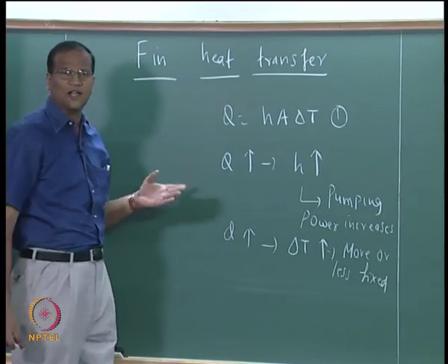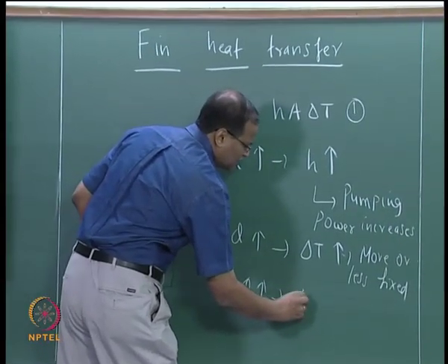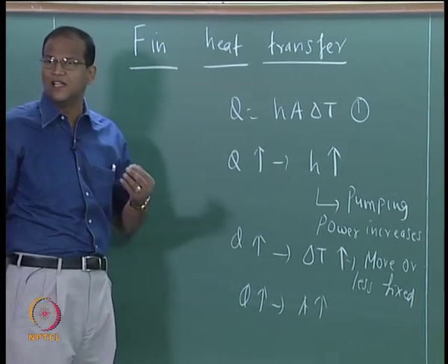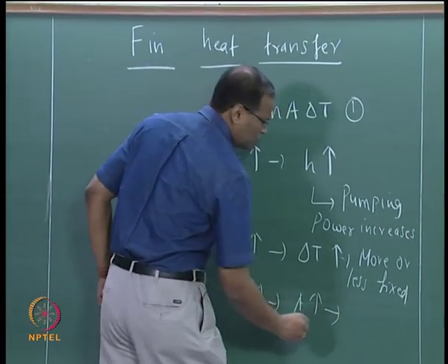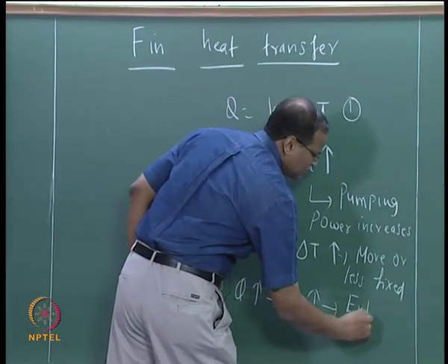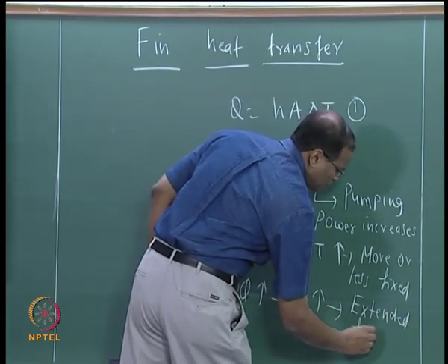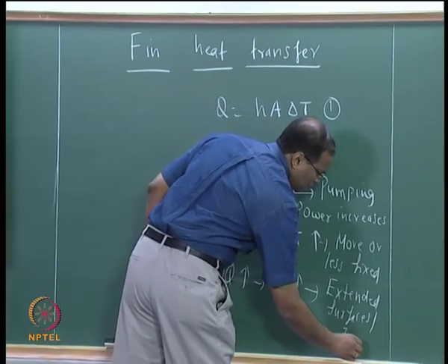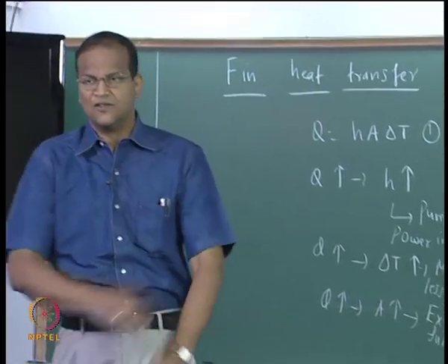So, therefore, most of the times the only option is that Q increases when A increases. That means you are augmenting the heat transfer by increasing the heat transfer area. So, you use extended surfaces. Right. So, the goal is to increase the heat transfer rate.